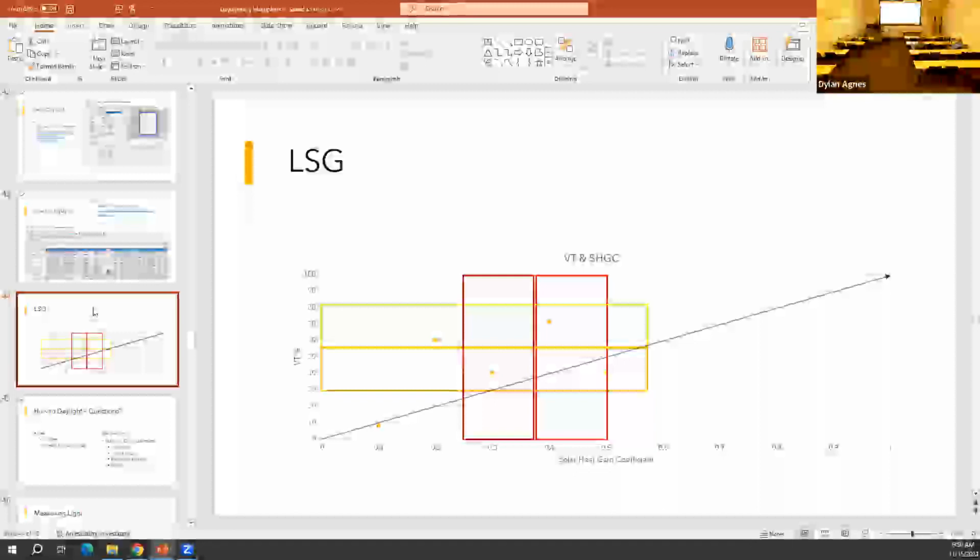Well, it's fairly old, as far as advanced natural, it's kind of like natural ventilation is something we figured out. Now it's more like we mitigate it. The bigger design change I've seen in the last decade is because of LEDs and how much less heat they give off compared to compact fluorescent or standard linear fluorescent. That had more than a marginal impact on the cooling and heating loads, so we actually had to rebalance and resize the HVAC systems for LEDs. We got it pretty narrowly dialed in, I would say, now.